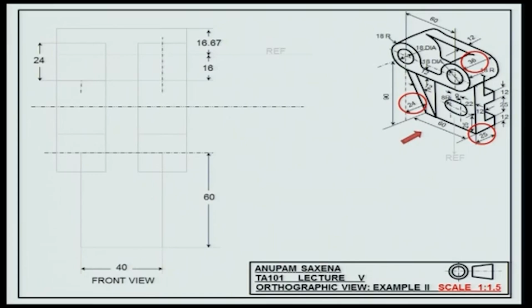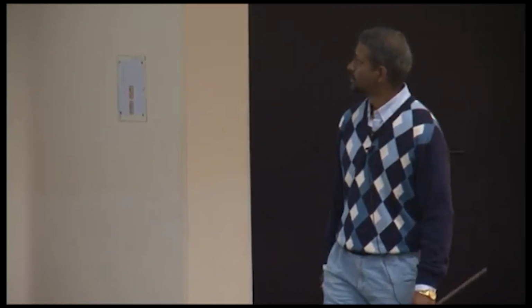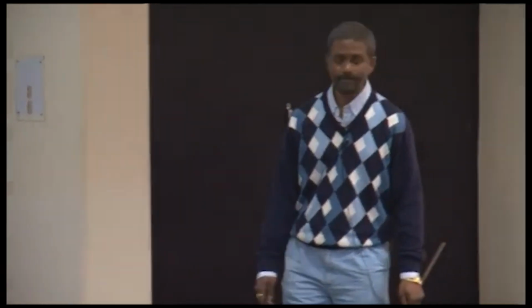Do the same for the other cylindrical feature as well. Of course, a cylinder is symmetric about its axis. You show the axes of the 2 cylinders using long dash, short dash, or dash dot, the convention that we have been using.